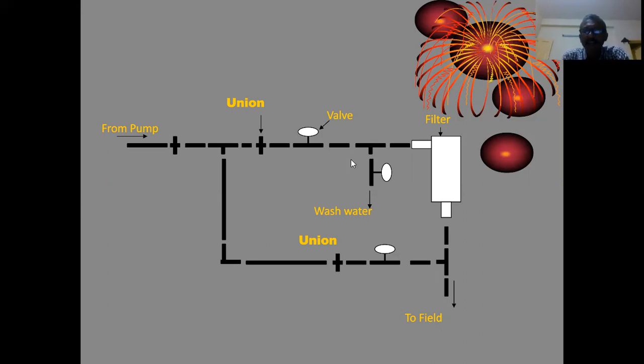So in order to have this kind of a system, you see how many small components are needed. See here on this side you have one union, a threaded connection, then a threaded nipple, then a T, then a threaded nipple, then a union. Then from here to here, to connect this valve and union, you need one more threaded nipple, and again on this side a threaded nipple and a T and a threaded nipple and a pipe section here with a valve.